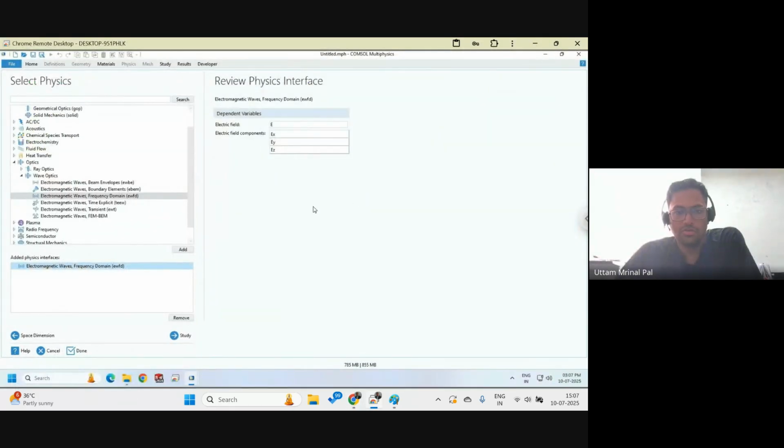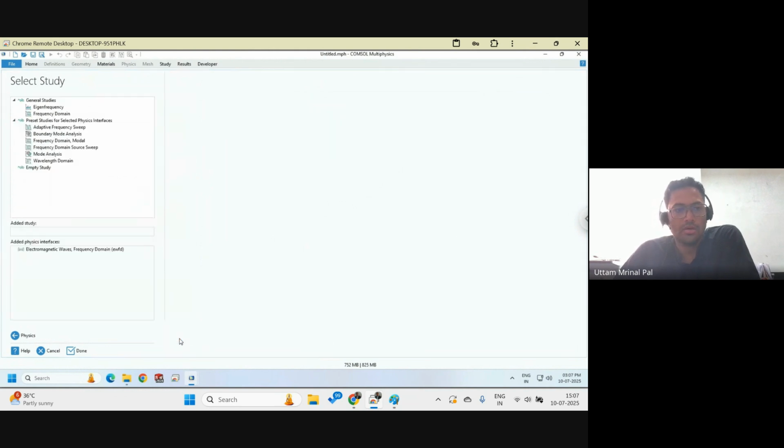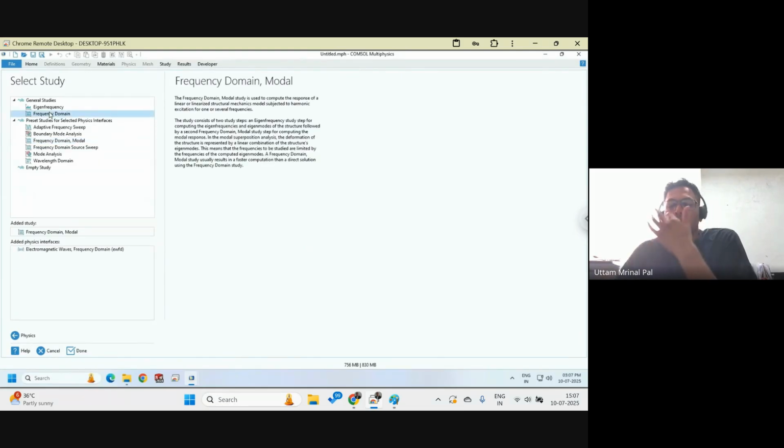If you have any questions, you can please unmute and ask. Should not be a problem. Okay, so you need to add electromagnetic waves frequency domain, then click on study, and then go ahead and select frequency domain study.